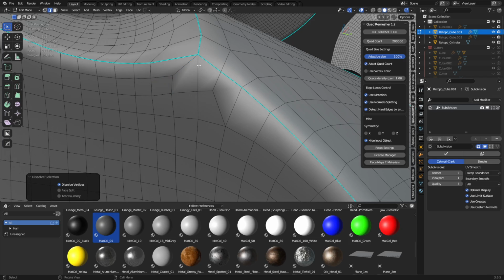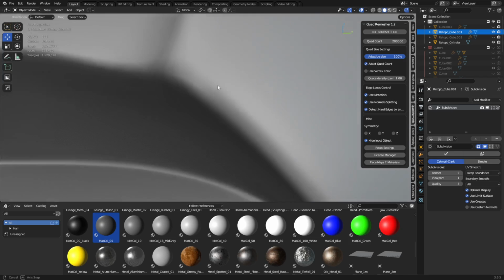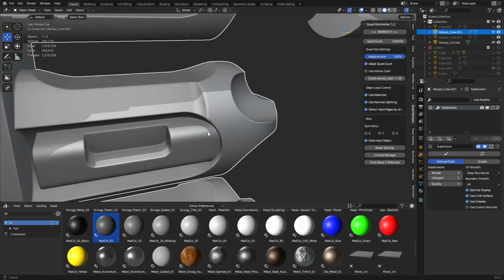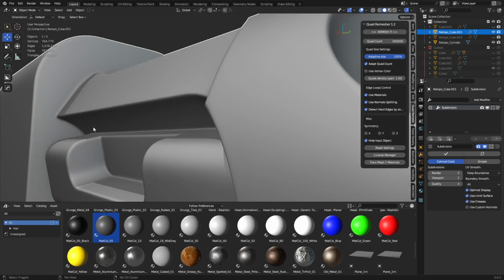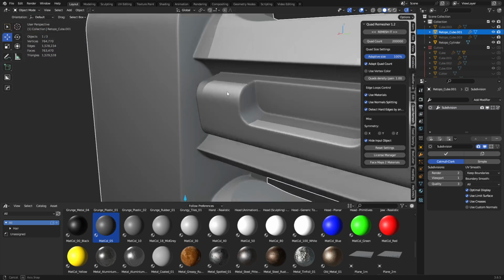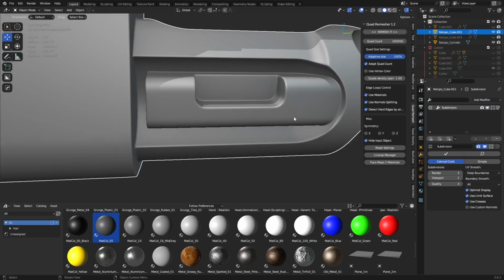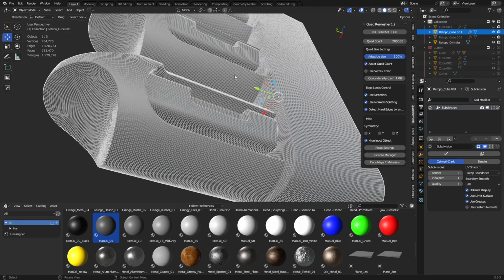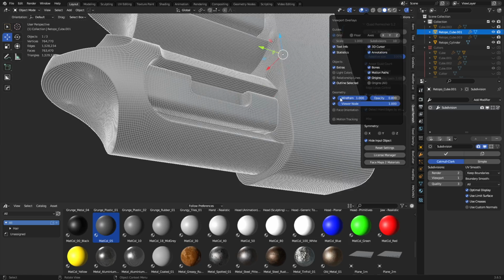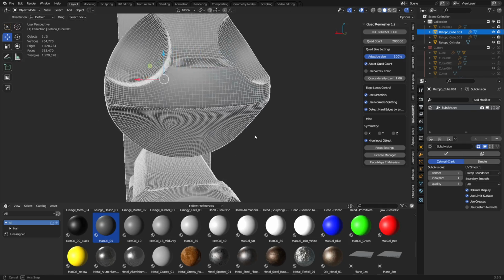Now that's going to create a little bit of tension in this area. So this has a big E-pole and it might look a little bit bad because of that. I'm going to show you another fix for that in a second, but some of this mesh might have done this in a number of different areas. So you do have to go back, check it, and correct it if needed. But you can see this is subdividing right now. It is quad remeshed. We are not running into any major issues for the most part, by the looks of it. Check the wireframe. If you're not using this wireframe, put it on a hotkey. It's quite useful, and we can get through this whole thing right now.